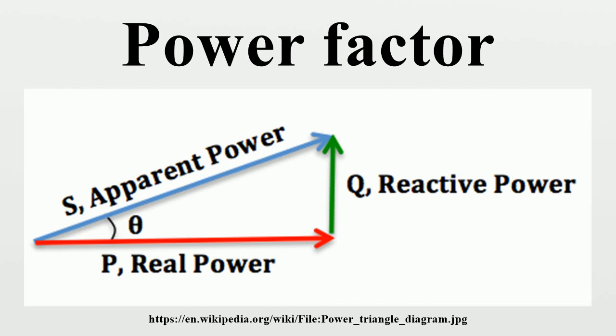The reactive power drawn by the synchronous motor is a function of its field excitation. This is referred to as a synchronous condenser. It is started and connected to the electrical network. It operates at a leading power factor and puts VARs onto the network as required to support a system's voltage or to maintain the system power factor at a specified level.